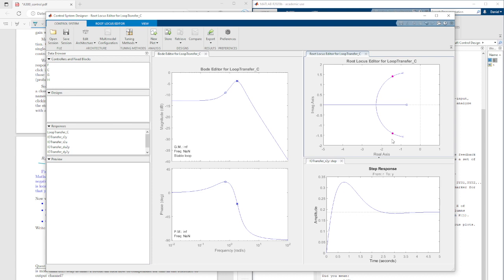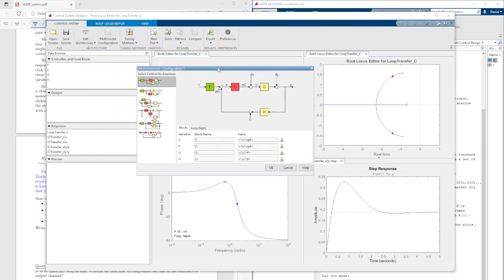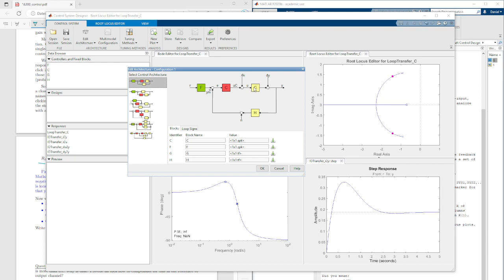but we'll get to that. Okay, the question is now, where's the gain, right? So how do we find our control gain? And this is what you find here on the left. If you click here on the structure, Matlab would open the block and show you what block means which structure here. We have our system G. We don't have anything for a sensor here. This is just one. And if we modify our controller, it's this block C here. This F, what you see on the left, would be a pre-filter. We're going to use that later.